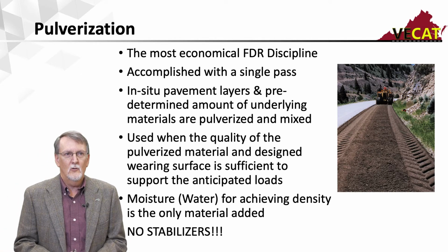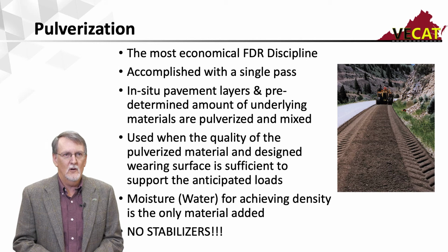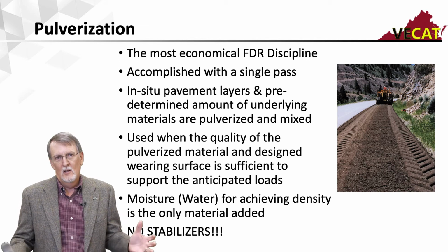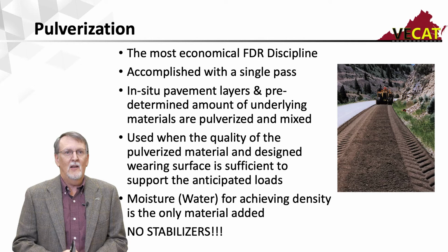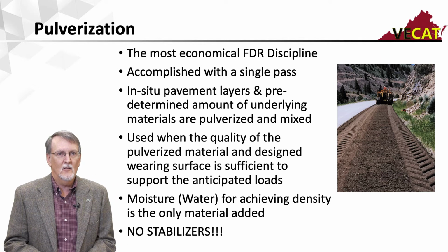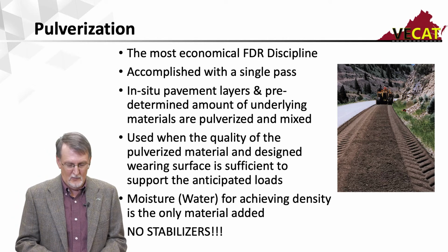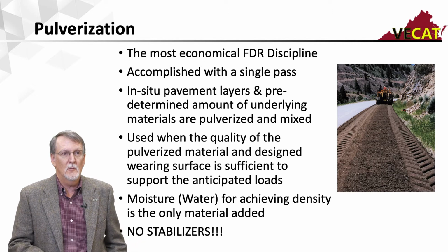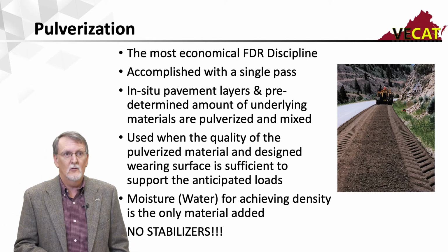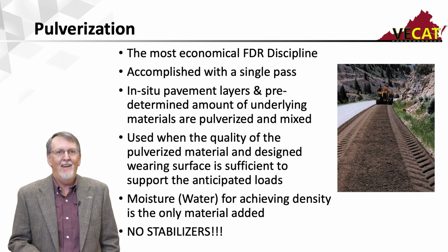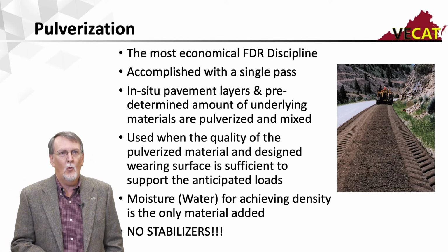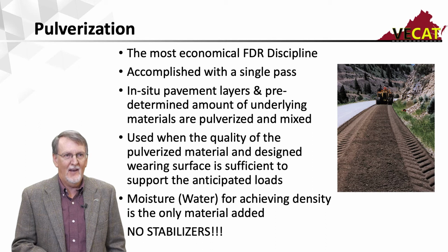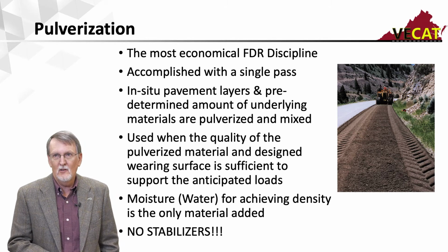Now, where would I want to use this? Well, there are lots of places where, with the pulverized material, you don't need to stabilize the base. With the quality of the material and the traffic, and the surface course you're going to put on it is perfectly capable of carrying the anticipated loads, then there's no reason to do this. The only thing we add to this process with pulverization is water, and that's used for compaction. There are no stabilizing agents used.